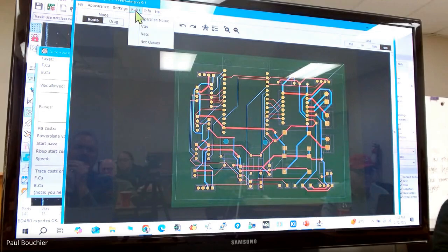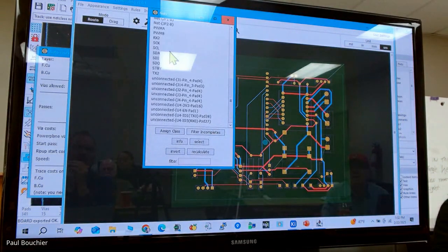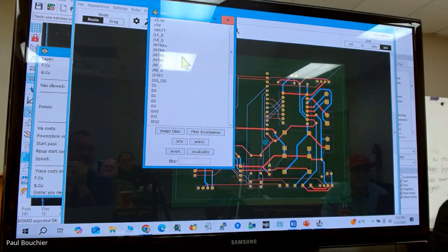And it has, let's see, here's all the nets, if you wondered what the nets were. These unconnected ones are where I have one of those little X's. So those are all the lines, which, by the way, is a good cheat for when you're in there trying to make way 3 of assigning net classes. So that's something to think about.